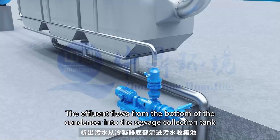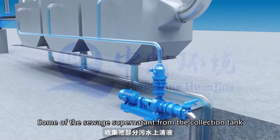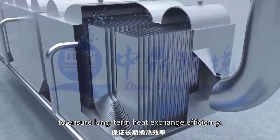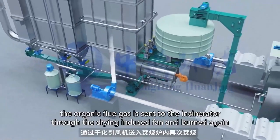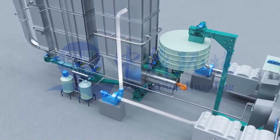The wastewater flows from the bottom of the condenser into the sewage collection tank and is pumped to the sewage treatment system by the sewage pump. The upper clear liquid of the collection tank is used by the circulation pump to flush the heat exchange pipelines in the condenser, ensuring long-term heat exchange efficiency. The flue gas, after removing moisture, is sent back to the incinerator for reburning by the drying induced draft fan, effectively solving the problem of foul gas emissions.